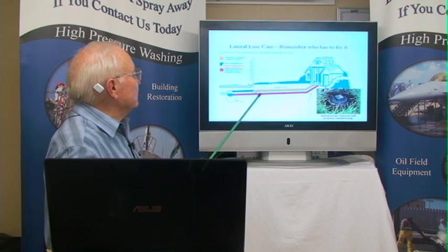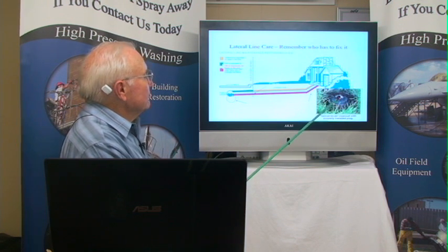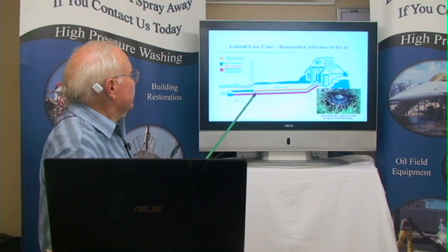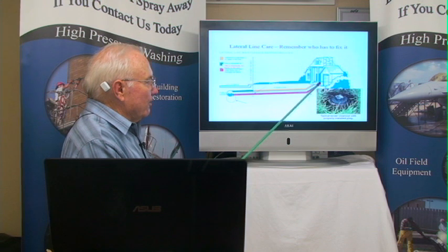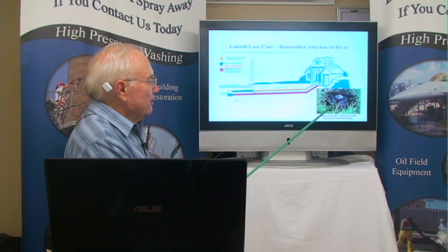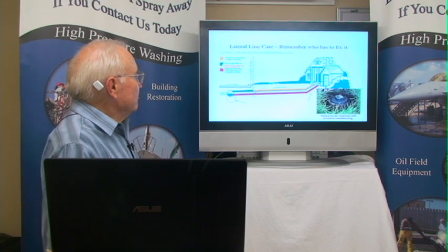That's if this line gets clogged up, that you can take that loose and clean out this sewer line. Now then, it's legal, since it's on private property, for the contractor to unscrew that and discharge into it with the property owner's permission.